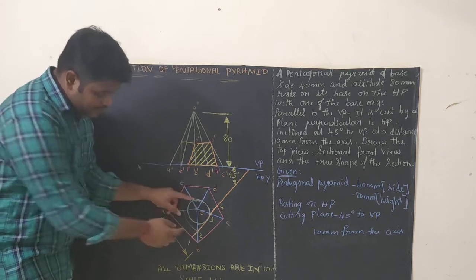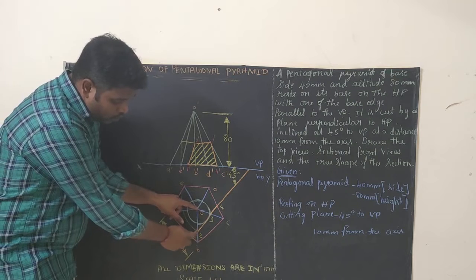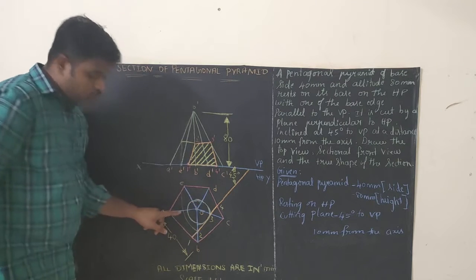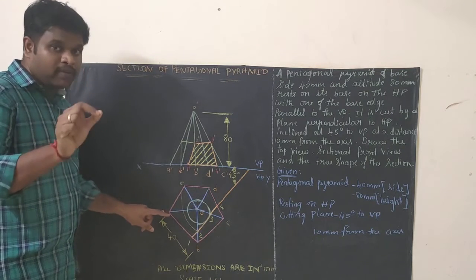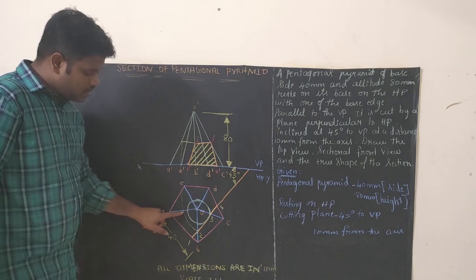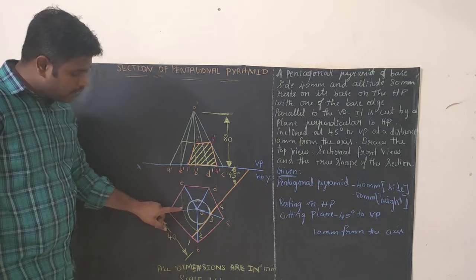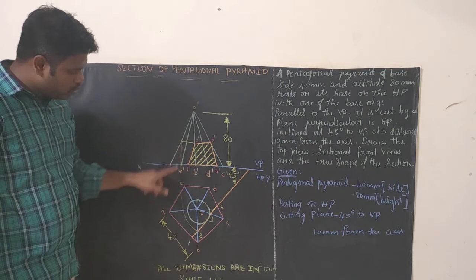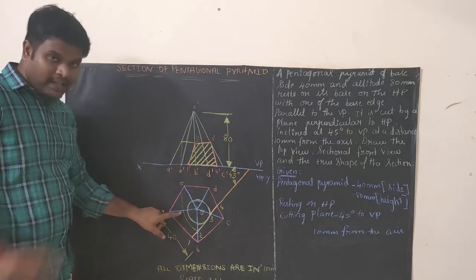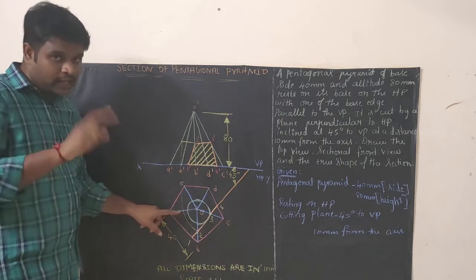with it as the radius. So the radius will be O to 2. Try to cut an arc to the nearest slant edge. Mark my words, to the nearest slant edge. So here you will be cutting, right? After that, take your scale and try to extend this line vertically to O dash A dash. So here you will be getting a point. That is, you cut an arc, right?